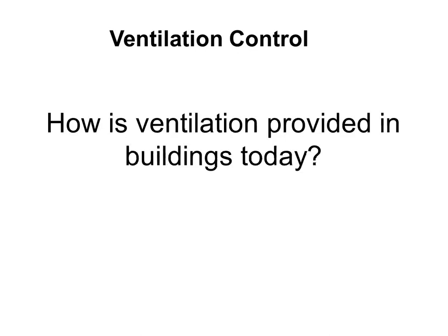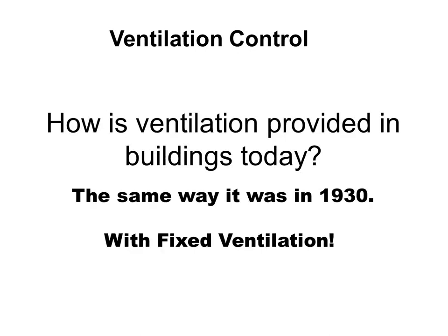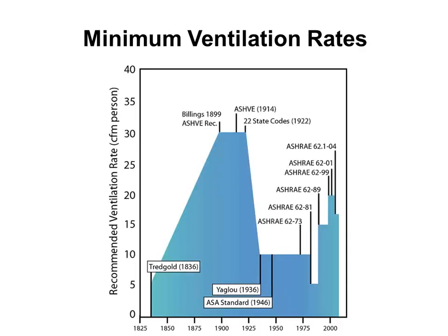All right, so ventilation control. And this is kind of a mini version of DCV. This is normally like an hour-and-a-half topic, but we're going to try to make it a 20-minute topic. So we control ventilation the same way we always do. We look at some book, some table. It says bring in this much outside air for this many people or this many square feet. Lock it in, leave it there forever, never touch it. That's typically what the codes historically have asked us to do.